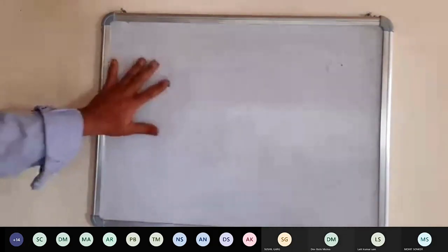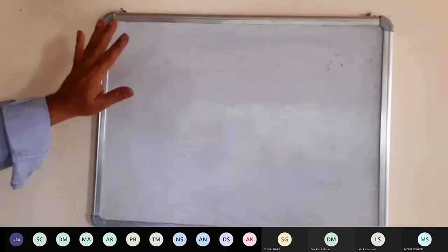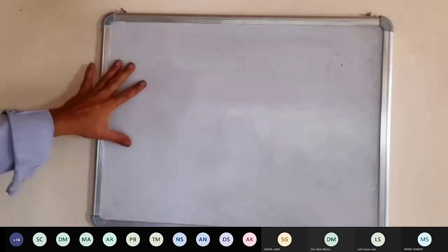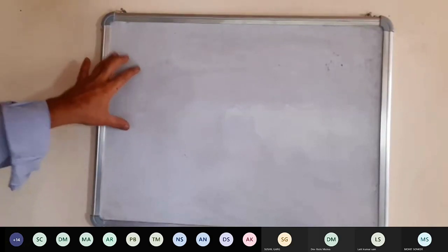Is that correct? Yes, sir. So that is the vertical soft iron, which is going to cause the trouble to the deviation to the compass. The most likely vertical soft iron is going to be the funnel, which is aft of the compass. So that is just for information.